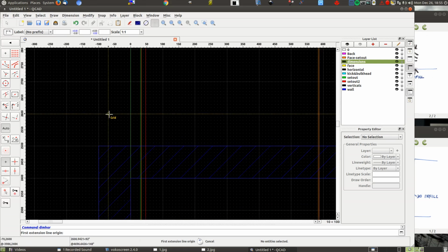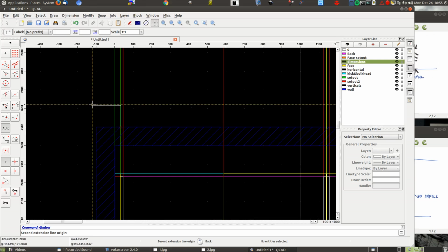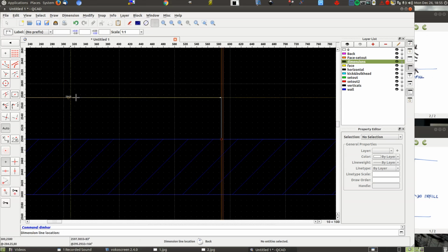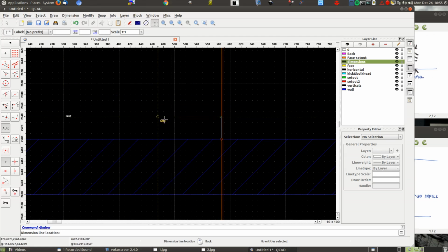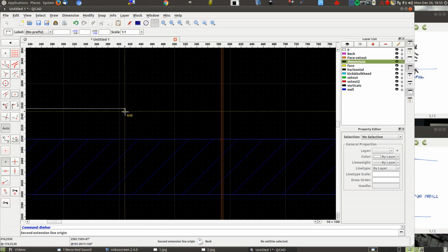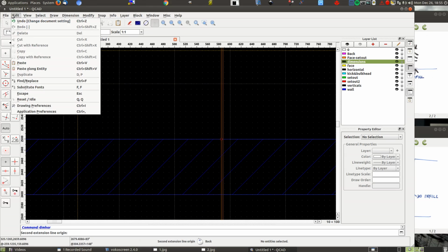Okay. I'm going to zoom in. The door starts from this edge and goes to that edge. But the number's wrong. Not clear enough. So we're in the middle of editing the dimension. And if I go right click, it takes it back one. So we're still in the middle of drawing the dimension. But QCAD is very handy. We can go and change those attributes.